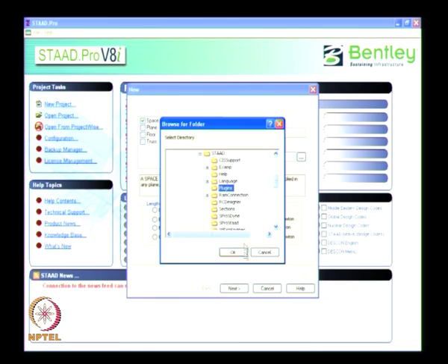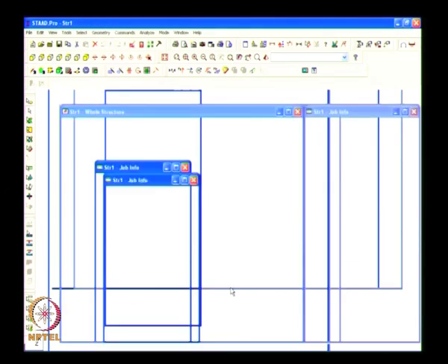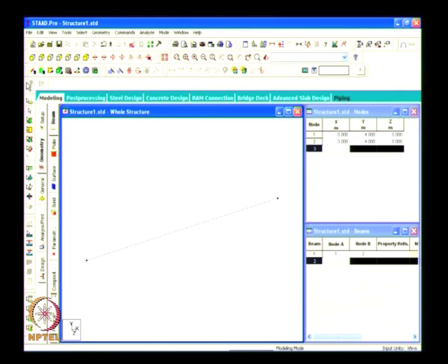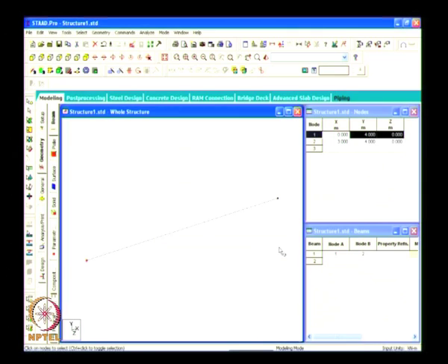Go slow. So this is the screen which you will be getting initially. In this plane we will be putting the piles, diaphragm wall and vertical pile and raker pile beams. Change the level to 3.85. Whatever it is, we generate.